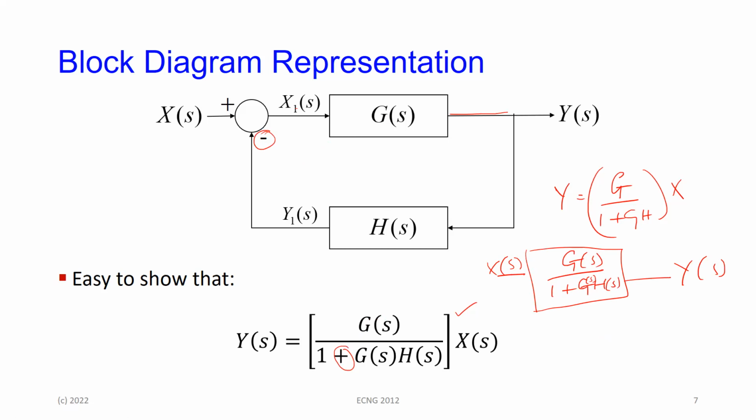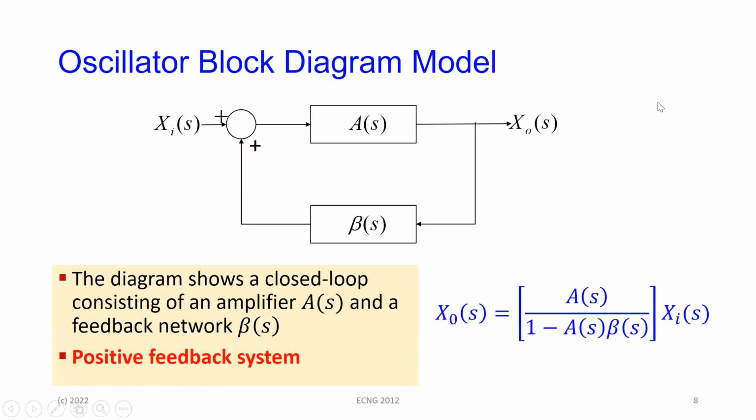Okay, so you take the block diagram, and what we've done is that this whole thing simplifies to X going into our block. This is the transfer function of the block, G over 1 plus GH, and Y coming out. All right, following me so far? Yeah, no, maybe? Make some sense, right? We've mentioned this in different forms a couple of times already.